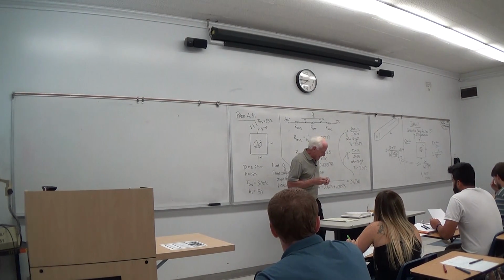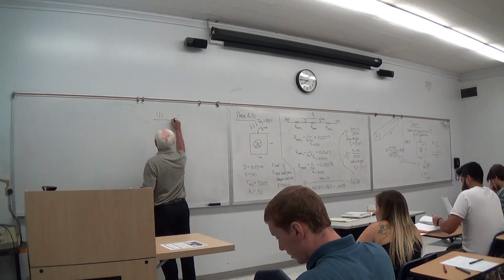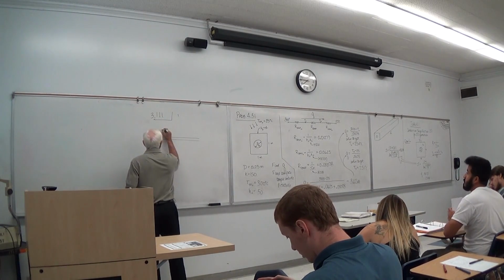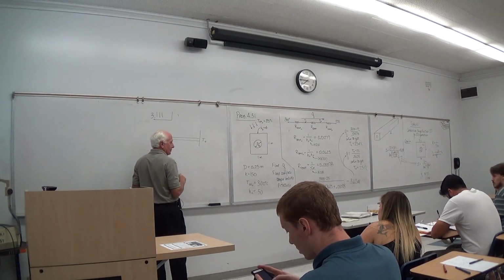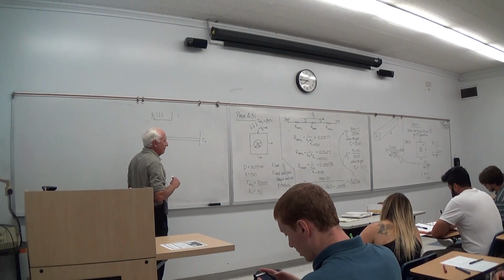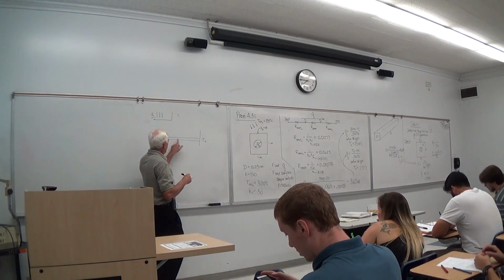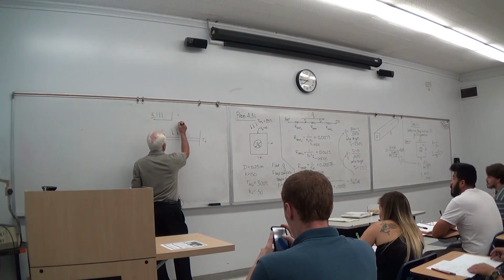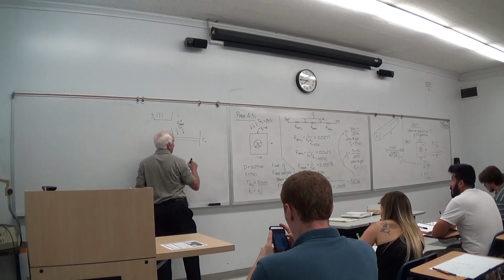Okay, now let's talk about problem 111, a solar collector panel. Here's the problem. There are tubes carrying hot water. The water in the tubes is at temperature T0. That's the base temperature of the fin between those two. The solar collector is a fin problem. We have heat transfer coming in, I think it's called Q radiation double prime, on a solar collector.